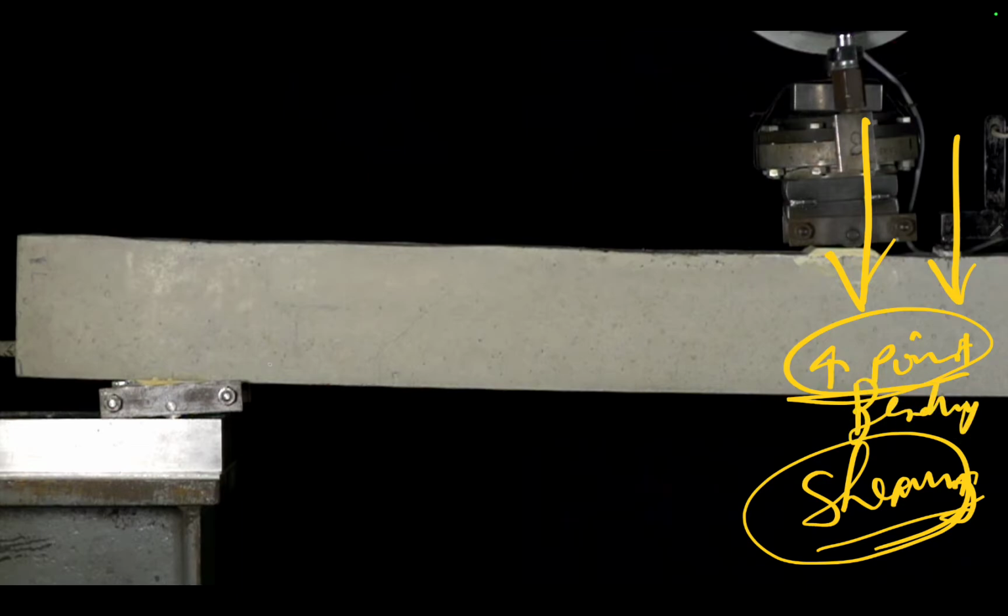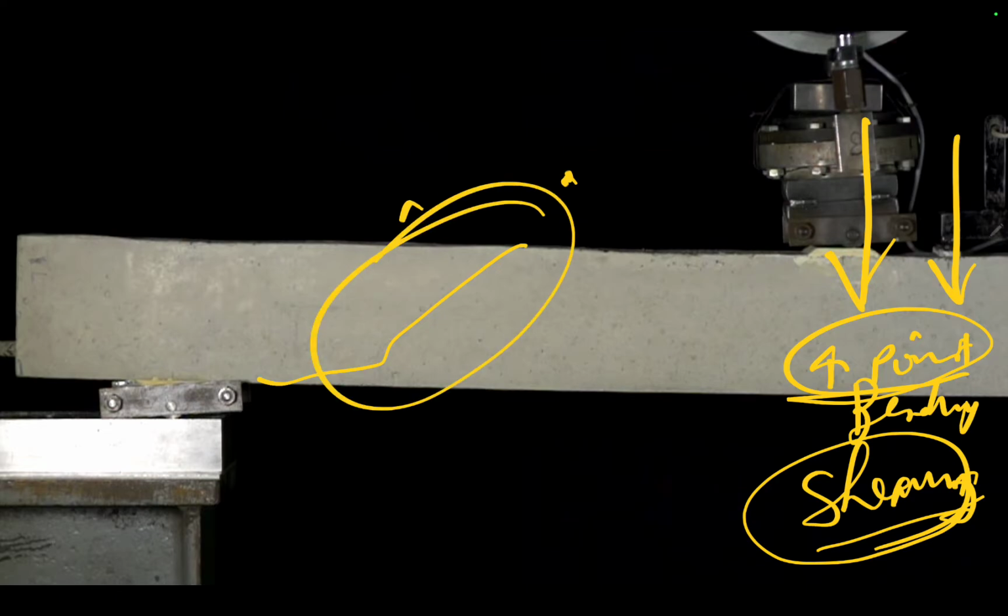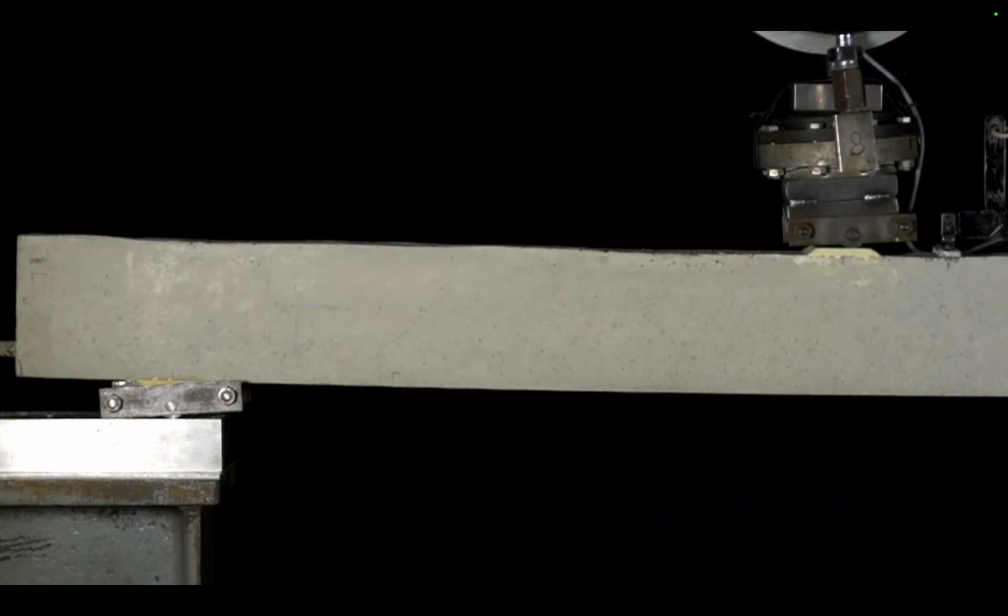But then when you see the crack, you say, oh, that's a shear crack. Wait a minute, you just said you put it in bending, and now you're telling me a shear crack developed. All right, tell me how. You just told me the stress you applied was a bending action, and yet you're going to say your test now is a shear test. It's not logical. I don't care what people think about what you're taught and trained. Oh, it's a shear crack. Yeah, it's close to the supports. Shear crack. It's close to the support. It's not at the support.